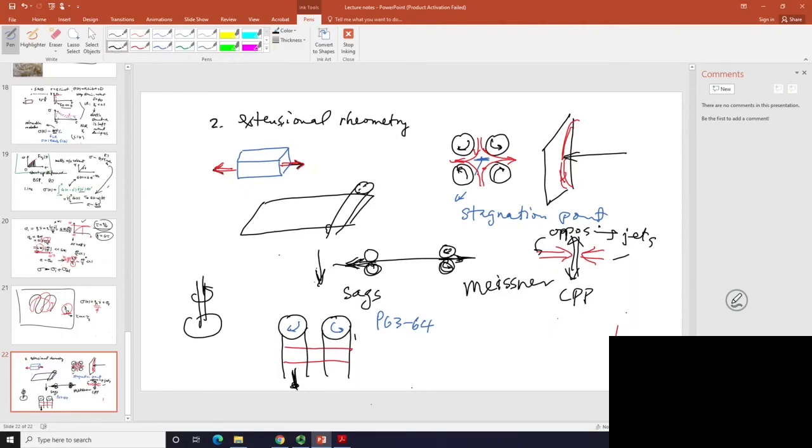Okay, let's see how it's different. Remember when we had the shear? We use this configuration to conceptualize and discuss it. If you have cone plate, it's the same discussion. I mean the shear plane has an area that is fixed during shear, right?